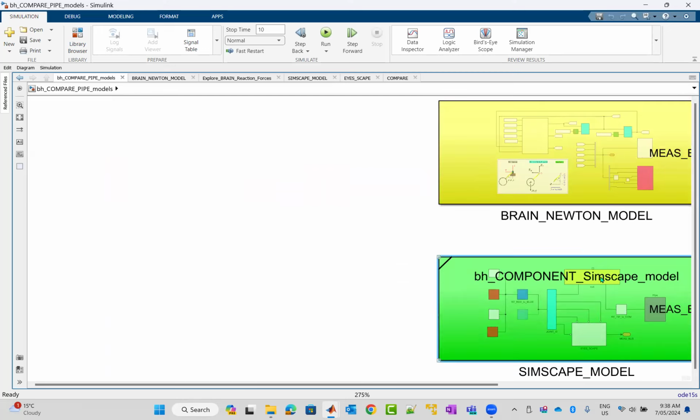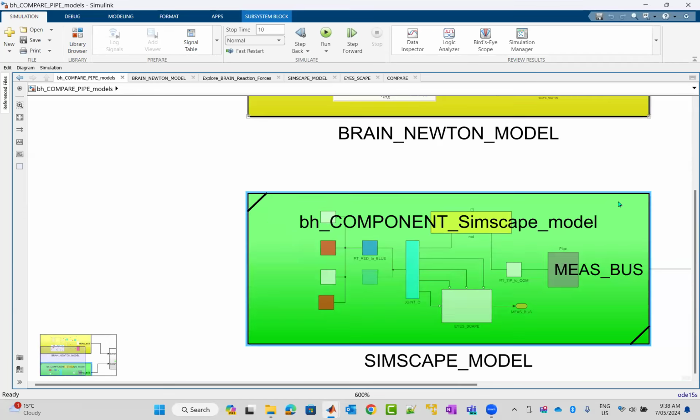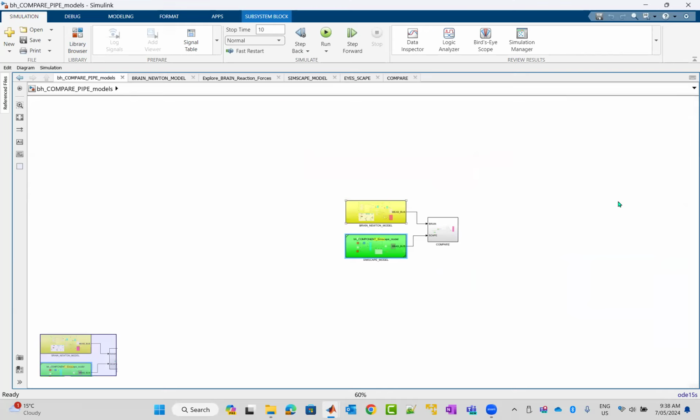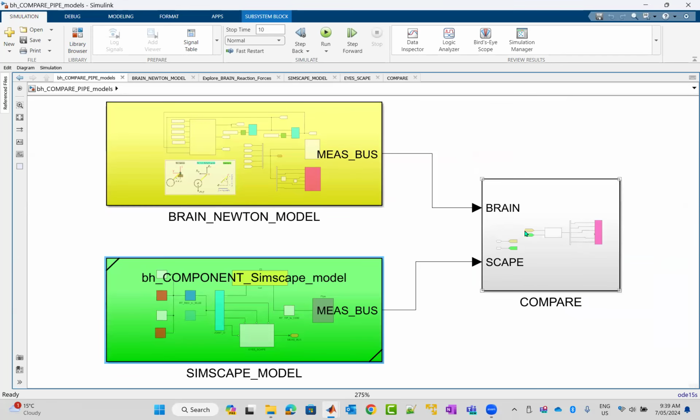Similarly, if you've opened a Simulink model and you've got your face pressed to the glass, so to speak, the shortcut keys for zooming out are Control and minus. And the last shortcut, which is the one that gets you out of jail 90% of the time, is to click anywhere white on your modeling canvas and then hit the space bar. If you're using a Mac, replace the Control key with the Command key.